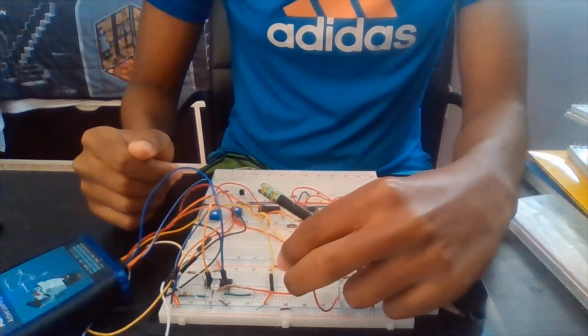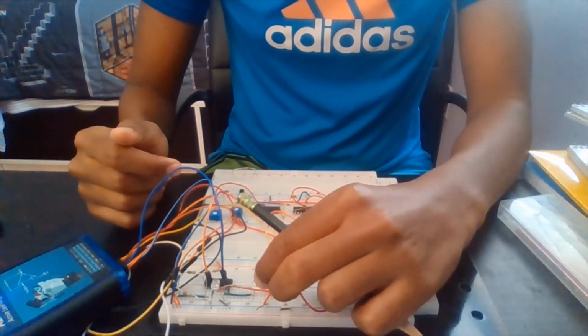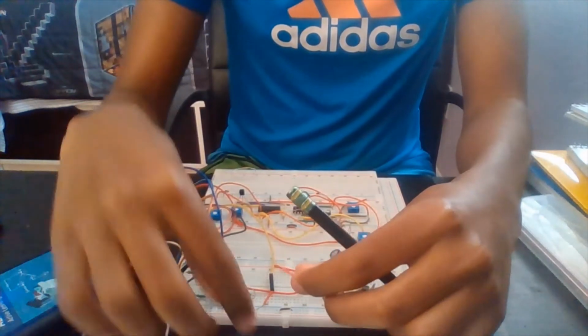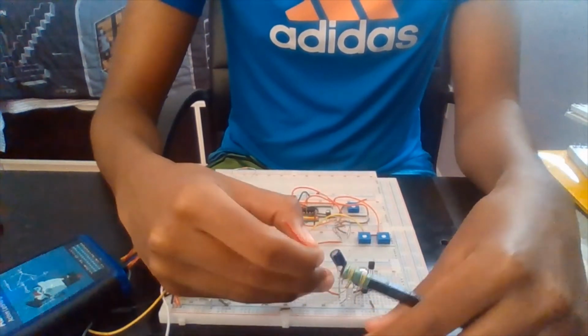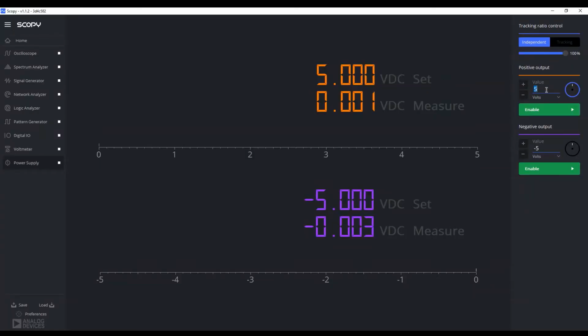Right, so now, just for this third subcircuit, I'm not going to be connecting it to the output of the inverting op amp. I'm simply going to connect it to, oh whoops, this wire just broke. Give me 1 second to change this. Alright, so now we're at Scopy. I just got a new wire and connected it to our power supply, so we can directly influence the voltage rather than relying on the light source, the voltage source of the LED. So let's just put in 3 volts, because that's what we recorded to be the approximate output voltage of the inverting amplifier.